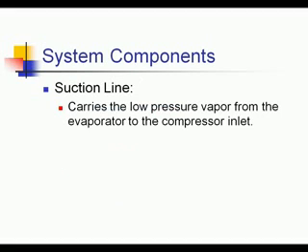And this is an evaporator coil. We have room air coming into the coil at 75 degrees. The evaporator coil is 40 degrees because of the low pressure refrigerant that's in it. The boiling point is 40 degrees, 69 psi for R22.